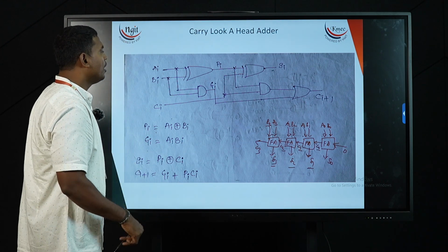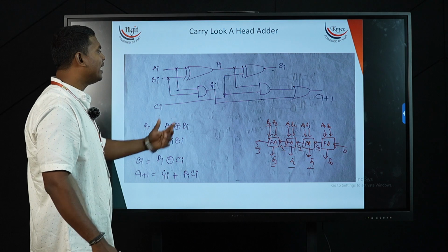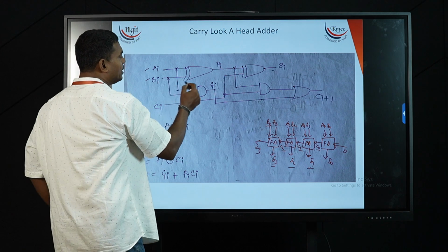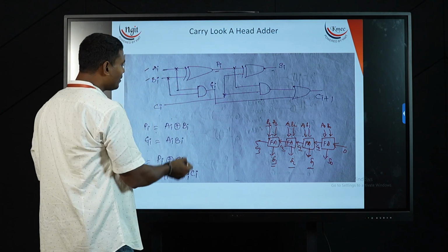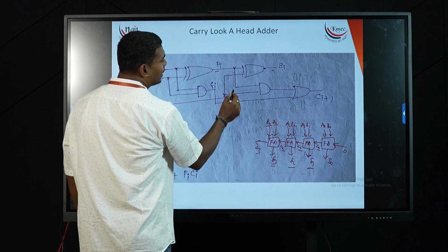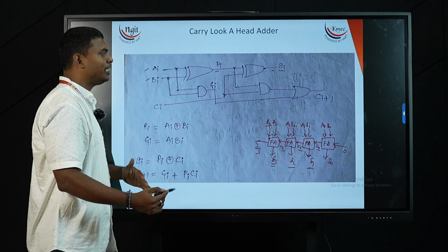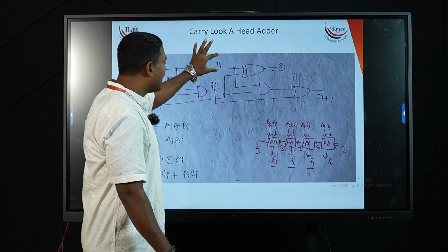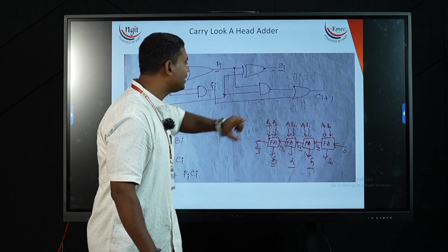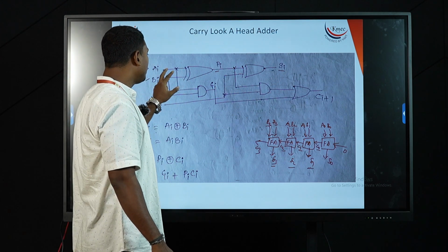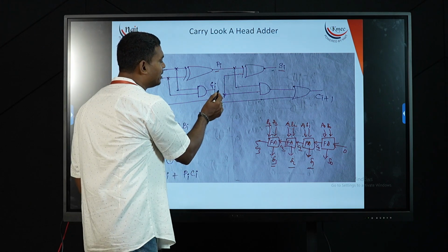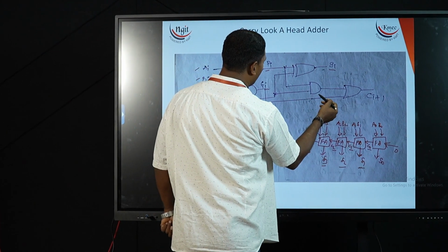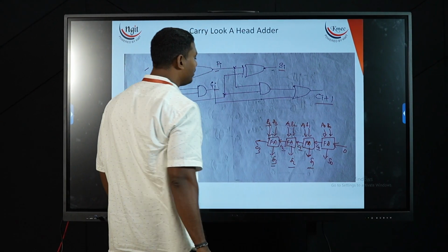Let's see. Now you know the full adder structure. This is a full adder structure where I am adding 2 bits, Ai and Bi, which generates Pi, and the third bit Ci is also added to generate Si. My variables are Ai, Bi, and Pi as the first sum; Pi along with the third variable gives me the sum, that is Si. Now the product of Ai and Bi I am representing with Gi. Along with that Gi, my value Ci is also added to give my carry value Ci plus 1.